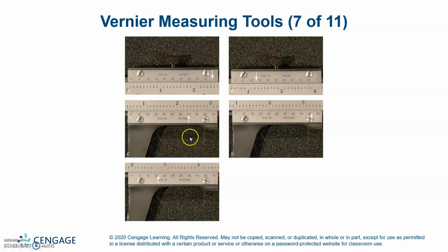And this is the same thing, except on this one, the scale is 50. So you only got one line in between the 100 thousandths marks. So we'll do A and then we'll continue on. We're looking at 0. It's before the 1 inch mark, so we're going to say it's 0 point. It's after this 6, so 0.6. It's before this line, so 0.6. But you just add the 35 to it. So 0.635. That's for the outside measurement.